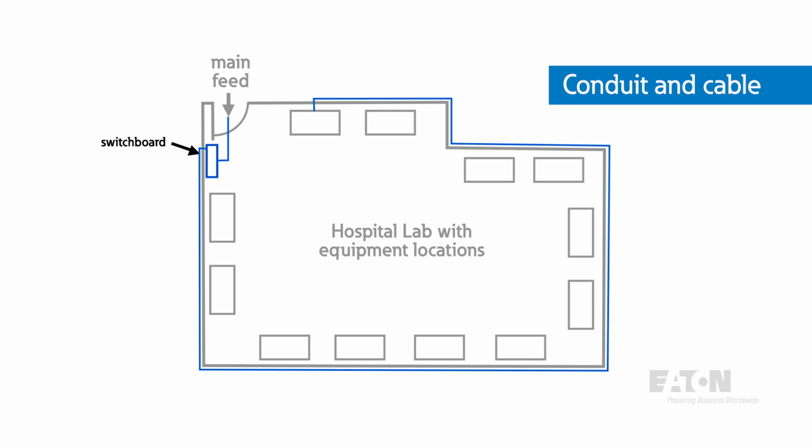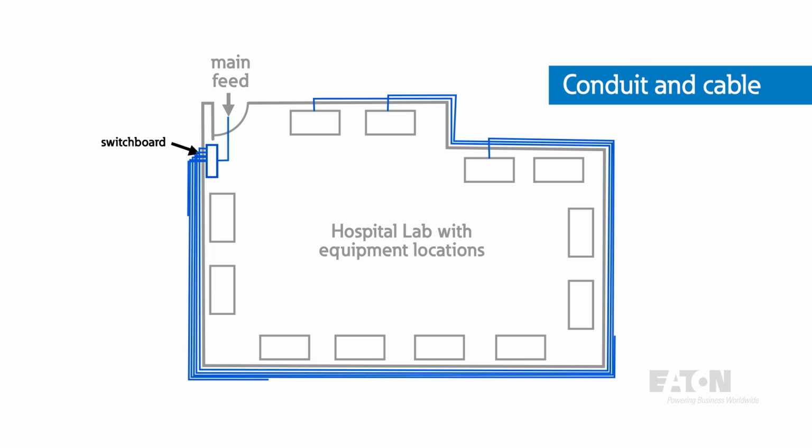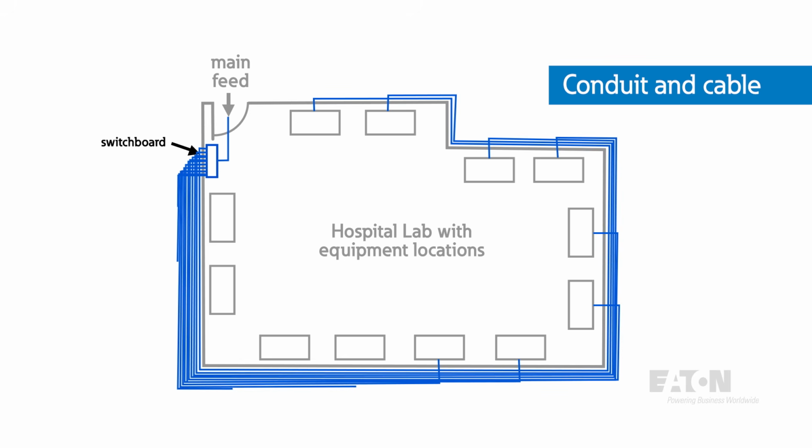Conduit will often need to be custom bent to odd angles and around corners to dodge existing infrastructure, then requires proper mounting and securing all along its length. Finally, cable can be pulled through. However, depending on its size and length, this alone may be an extremely difficult and involved process. This conduit and cable installation procedure then needs to be repeated for every additional piece of equipment, with each run having less and less space and needing to dodge previous ones. It can be a major challenge to just plan out every cable and conduit home run.